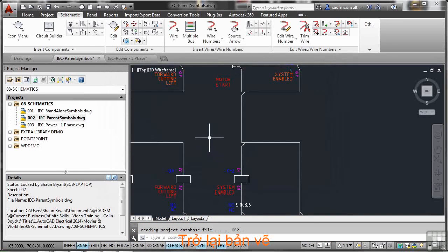So be very aware that AutoCAD Electrical works in the background, allowing you to work these things out. You don't have to do them in your head. If you overload a 2 contact symbol, like my relay coil, it'll tell you when you try to insert that 3rd contact and link it to the same relay coil in the same project. It's a very, very handy feature. Stops you making mistakes. It removes that manual component to any electrical drawing by allowing you to automate what you're working with.